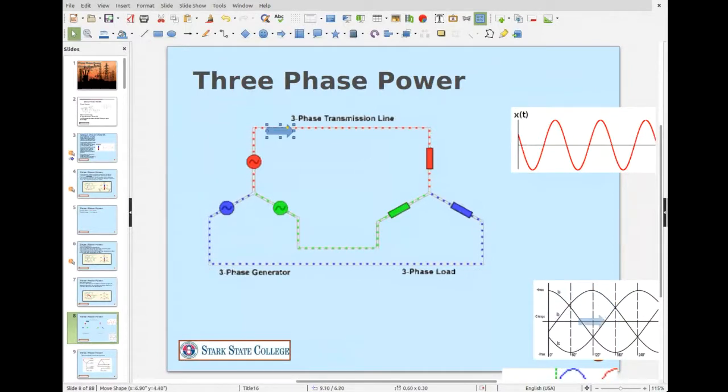All right. And then as the third one starts going up to its maximum, then the other one was at its, and where these two are equal, where phase B and C here are equal, phase A is maxed out as negative. Okay. And so they're always pushing, so when A is the highest, it's pushing down this way, and it's going to push the current into either phase B and or phase C. So watch this.